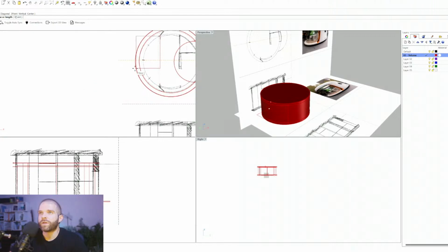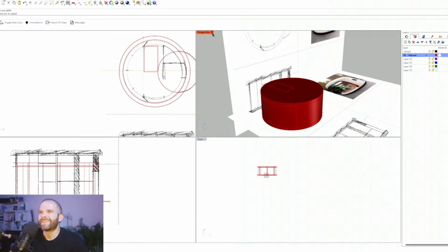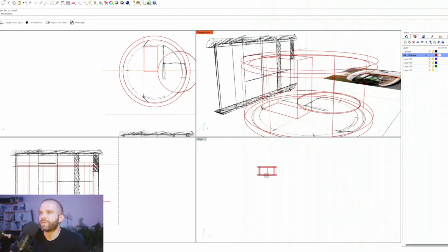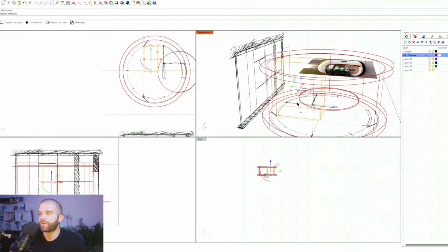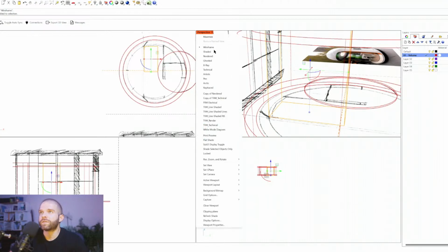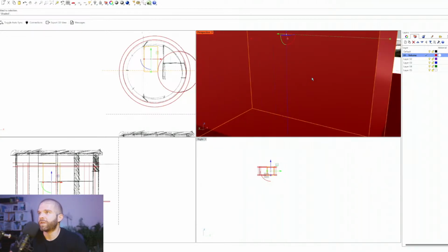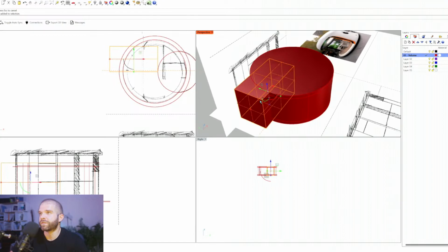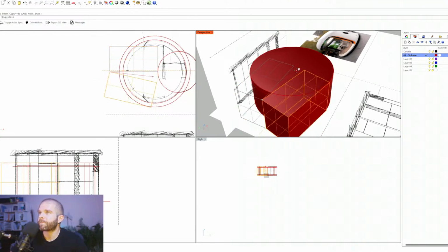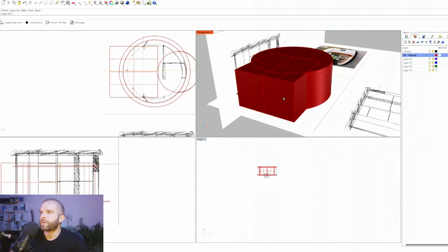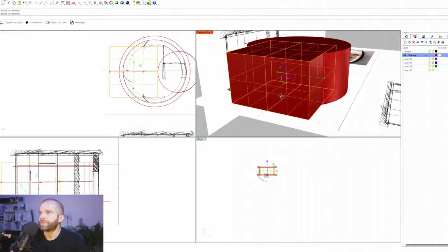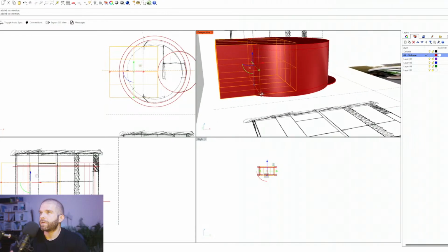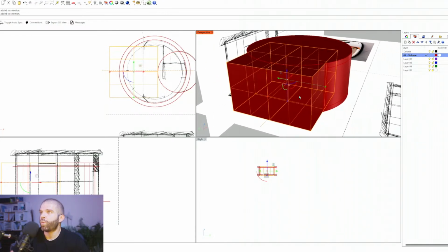And we're actually going to snap this only to the middle of the sphere or the cylinder. The reason for that is we want it to be the exact same size on both. So the way to do that is we're going to just do it on one half and then mirror it over to the other. That way we make sure that it's centered. So we do mirror now. Boom. Now actually, I think this would be wider. Cut through it a little bit wider.